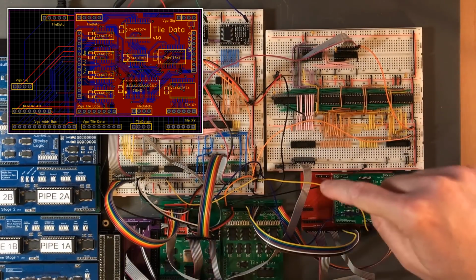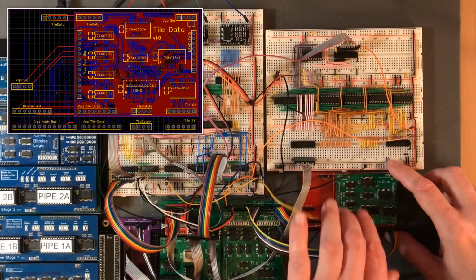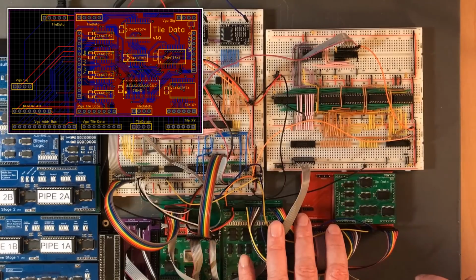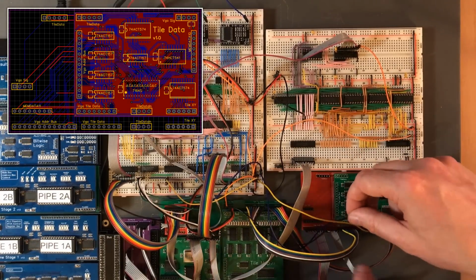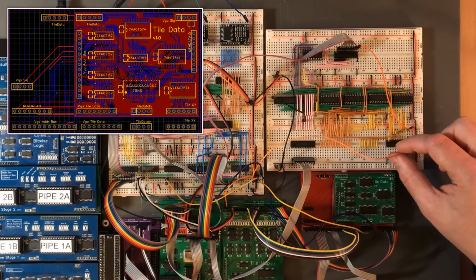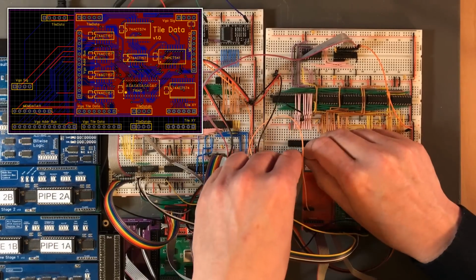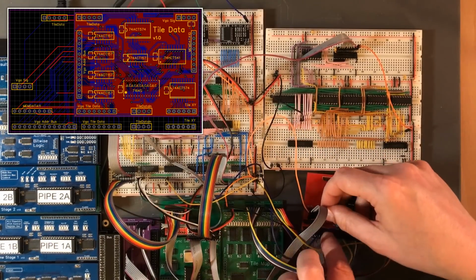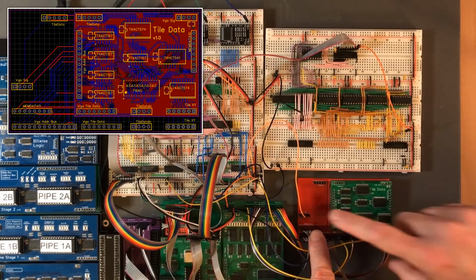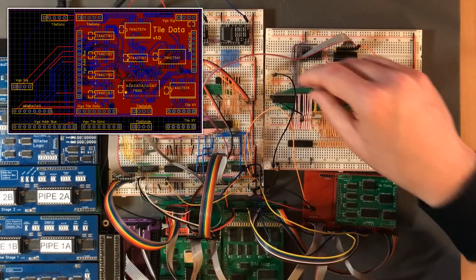Now both of those signals actually just originate from on here, so I would like to get the wires sorted to go direct. I've only got the one output for the memory load line, so I do have to multiplex it over here. Okay, there's an extra ground tie. Can make use of that there. Right, that's the clock line. That goes there. And this will be memory data. Let's not forget that. Now we've got the outputs, but we've got power and ground in here as well. Might be worth looking for a longer one there.